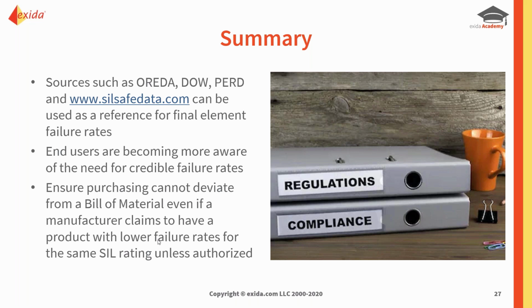I mentioned this already, that end users are becoming more aware of the need for credible failure rates. Because again, if we say that the SIF has a much, much better PFD average than it actually has, then we could be fooling ourselves into thinking we've got more risk reduction than we have.